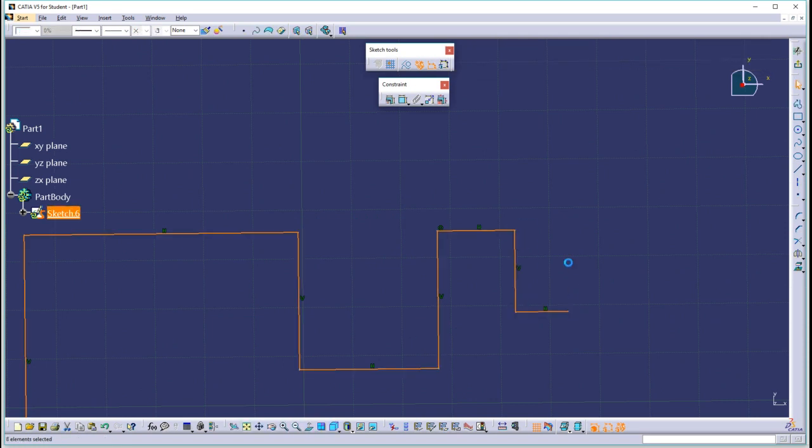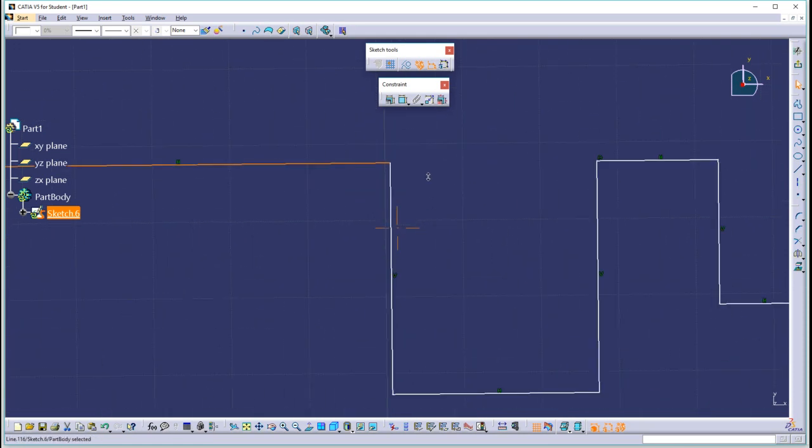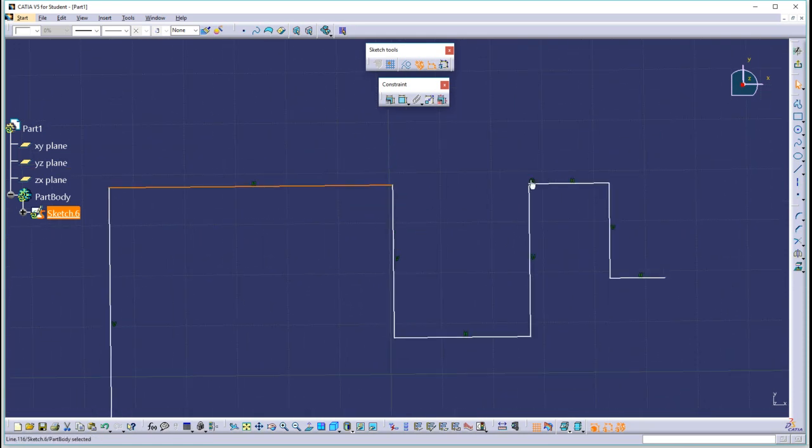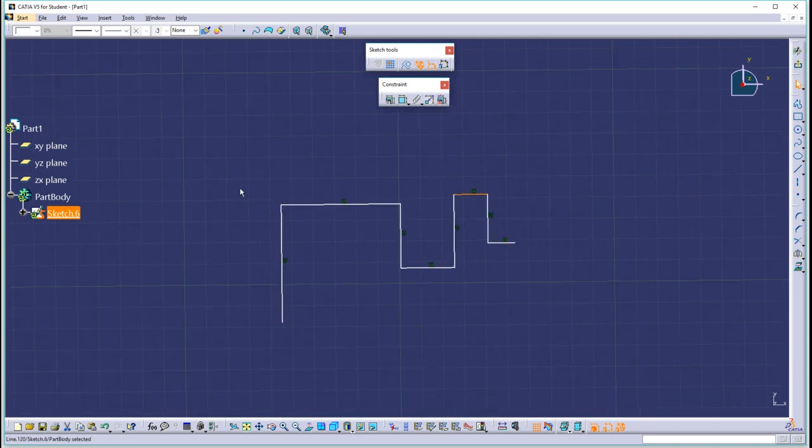Let's double click. So now if I change this line, if I move it up and down, those two are tied together by that coincidence constraint. Notice the little ball that's there, and that goes to a little ball that's over there. If I delete that, then these two move independently. It's really nice to have those detections a lot of times as you're drawing geometry.